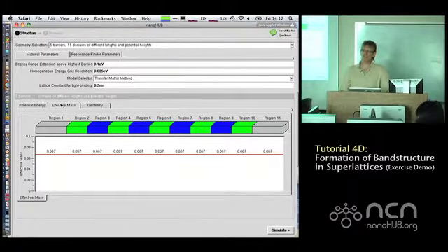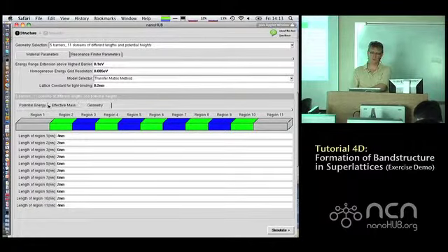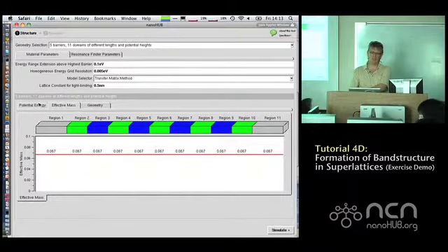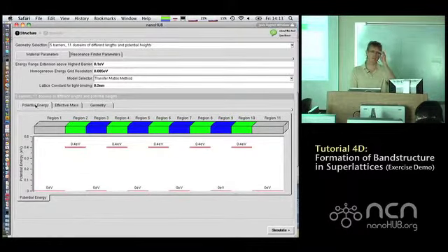So this is a teaching tool, right? This is a tool for concepts. If you want to do a real RTD, we'll go to the RTD negative tool, and you will say, I want to do aluminum gallium arsenide at an aluminum percentage of 30%, and it'll pull out what the conduction band edge is and the effective mass. This is a teaching tool for understanding potential barriers, etc. So you have 3 choices. You can change the geometry, so the length of these regions. You can change the effective mass and the potential energy.